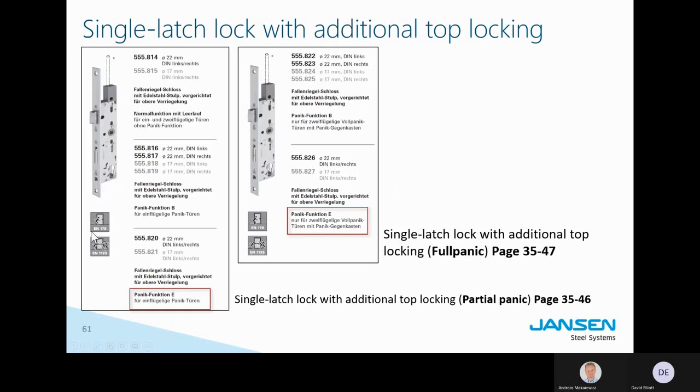When you are in a totally public building, like a shopping center or a movie theater with a high number of users, you have to follow the European norm 1125, and here you always have to have the push bars. The doors have other requirements. They have to always open, they have to be marked and lit, and so on. So norm 1125 has more requirements. It's the stricter norm, and it applies to public buildings where the users don't know the way out.